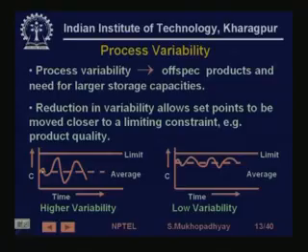For the product to sell, you need a certain quality finally. In the case of storing in tanks, as we have said, if you have widely fluctuating product quality, then you actually need a large tank, such that when all these variations come to the tank and finally get mixed, they come to an average quality. If you have a small tank, then obviously integration over a smaller time of a sinusoid will still give variations. So, if you want to reduce variations, you will need to have large tanks.